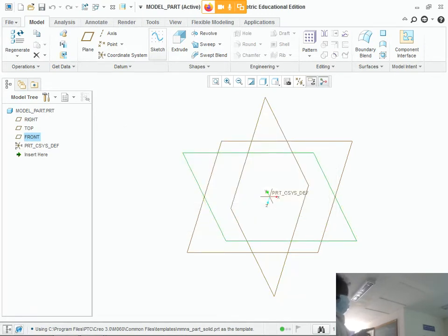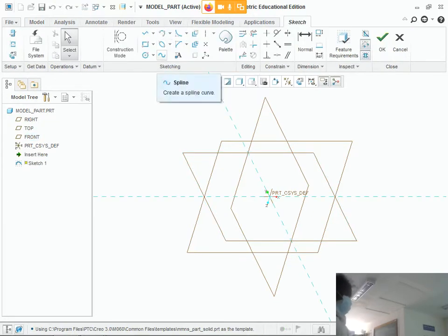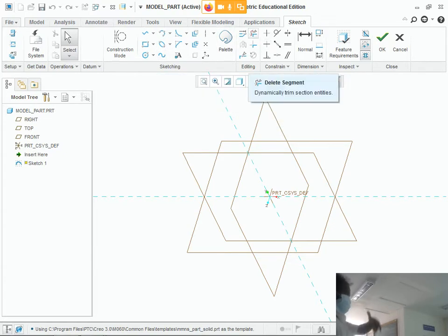So once you choose the sketch, you can go to sketch. Once you have chosen the frame plane, you can go to the sketch, and once you click the sketch, you have so many options that open under the umbrella of sketch. So you have, say, a line, or a square, a circle. Say this is a 3-point arc that you can draw, an ellipse, and so on and so forth. All these options we are going to use one by one.